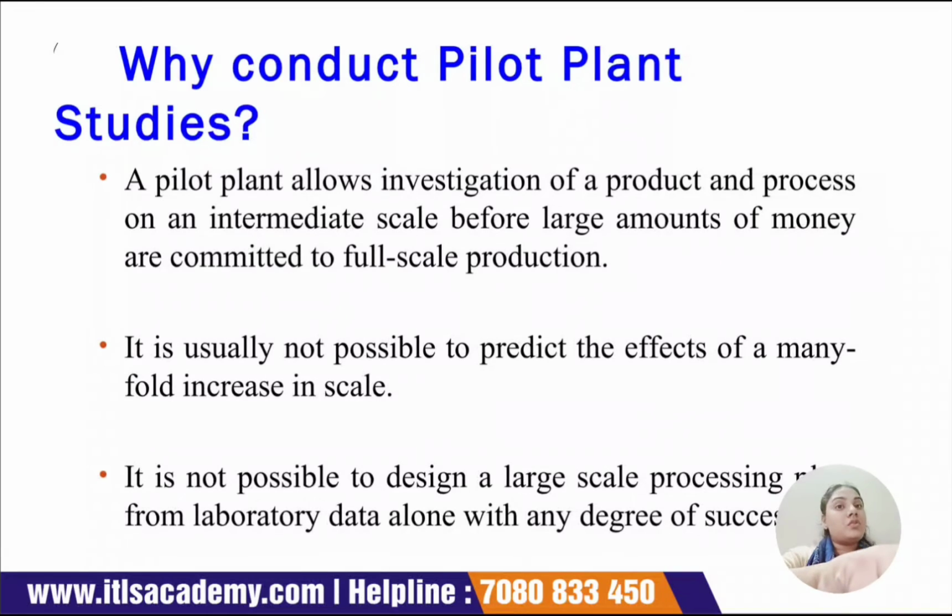Then comes the important heading from the interview perspective: why conduct pilot plant studies? That means what is the need to conduct pilot plant studies? A pilot plant allows investigation of a product and process on an intermediate scale before large amounts of money are committed to full scale production.